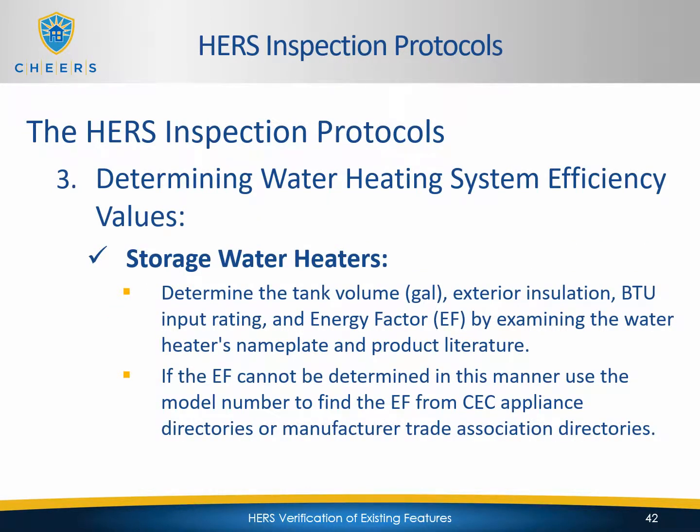Storage water heaters. You want to determine the tank volume in gallons, exterior insulation, BTU input rating, and energy factor by examining the water heater's nameplate and product literature. If the energy factor cannot be determined in this manner, use the model number to find the energy factor from the CEC Appliance Directory or manufacturer trade association directories.